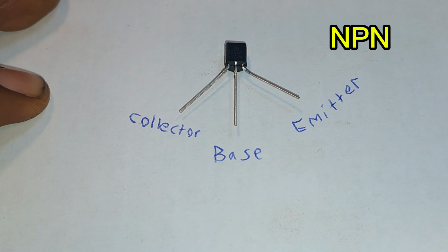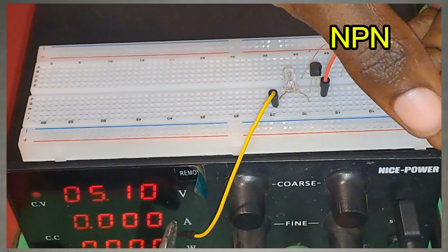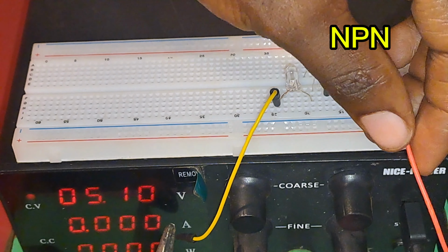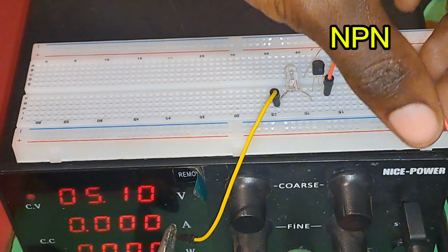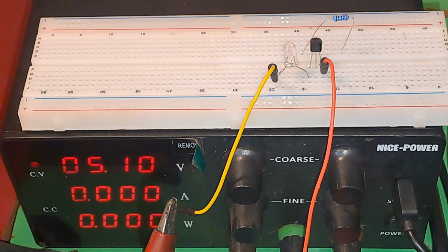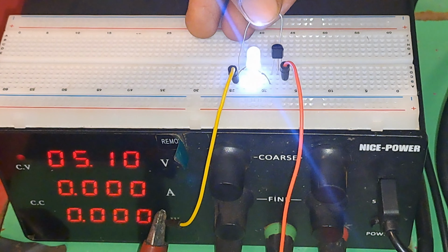By connecting the collector to a 5 volts power supply and the emitter to ground, which is very safe because it does not exceed the maximum voltage rating of this transistor, I then connected the LED between the positive voltage supply and the collector of the transistor. Here nothing happens. All that you need is to pass some current through the base of this transistor.